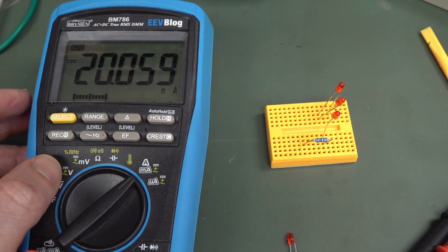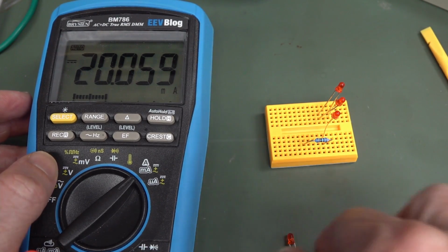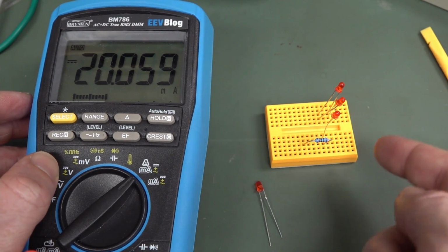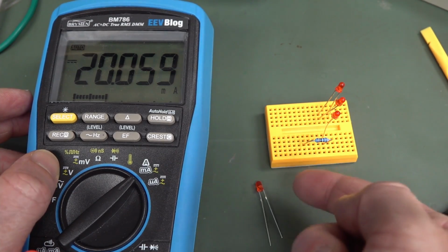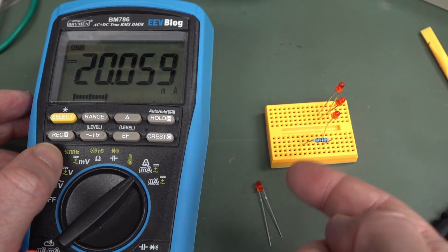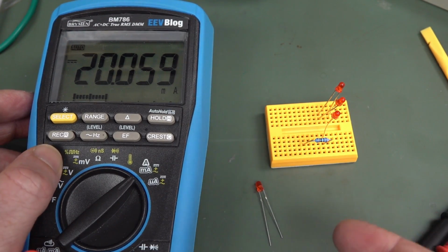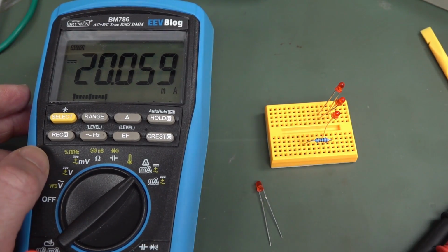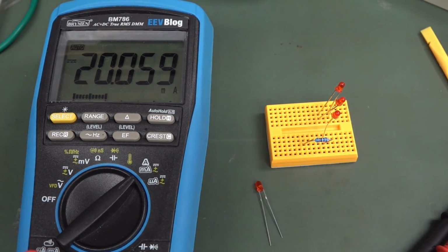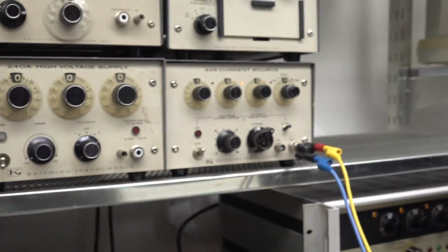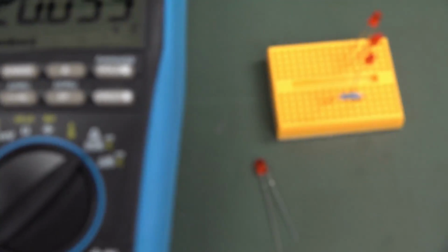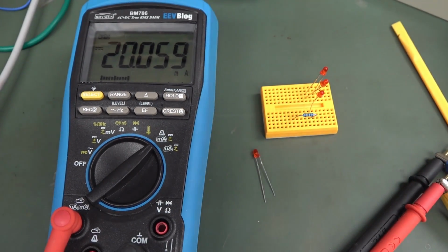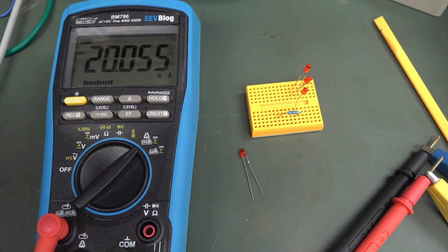Oh, all right. I know people aren't going to be happy unless they actually build this thing up. So I've actually managed to find, after some searching, 4 red LEDs that are pretty damn bang on 2 volts at 20 milliamps. And trust me, it wasn't easy to find, but I found them. Anyway, I'm using my external Keithley current source here. I've set that to pretty close to 20 milliamps. It's only a 3-digit adjustment, unfortunately, but that's good enough for Australia, right?